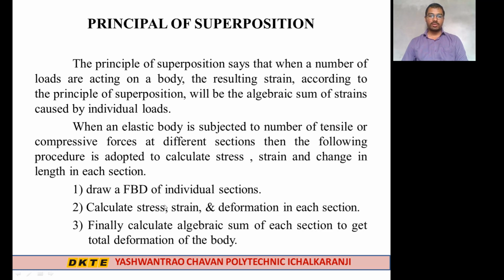We have studied the formula: stress is force upon area, so using that equation we are going to calculate the stress. Strain is change in length upon original length, and deformation is PL upon AE. This is the formula. In each section we will get different stress, different strain and different deformation, because the loads are different on each section.